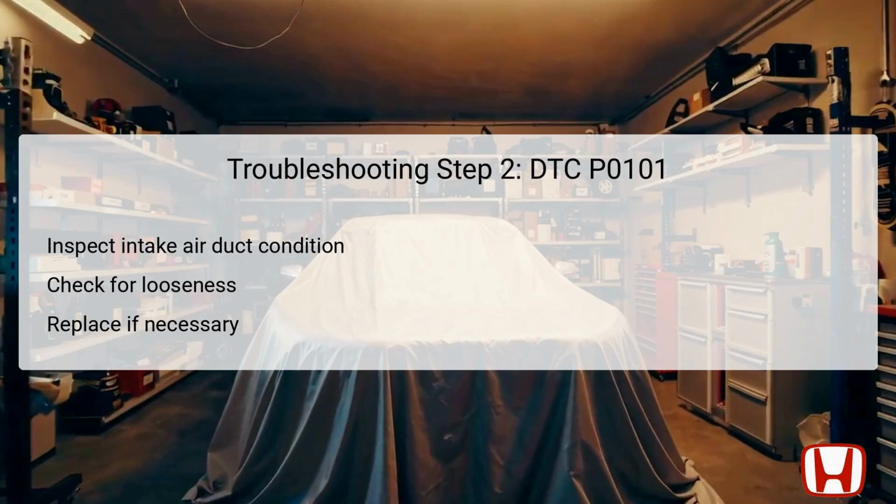Tight connections are vital to ensuring that all airflow is correctly measured, and any issues found must be rectified immediately. If the intake duct is damaged, it will need to be replaced. Upon confirming that the duct is in good condition, continue with further diagnostic steps to isolate the issue effectively.